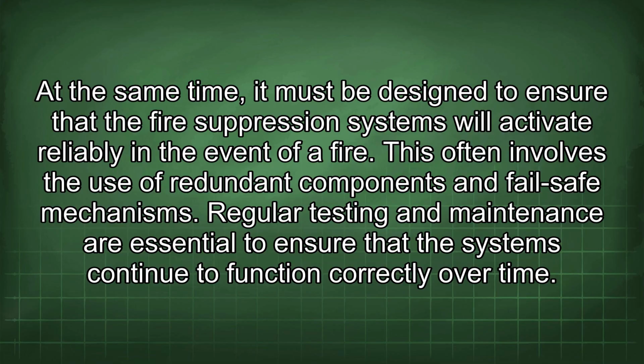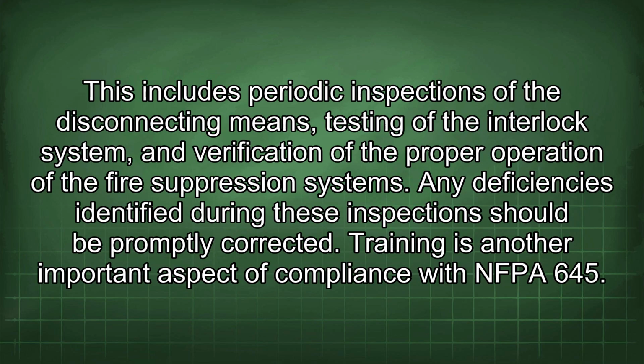Regular testing and maintenance are essential to ensure that the systems continue to function correctly over time. This includes periodic inspections of the disconnecting means, testing of the interlock system, and verification of the proper operation of the fire suppression systems. Any deficiencies identified during these inspections should be promptly corrected.